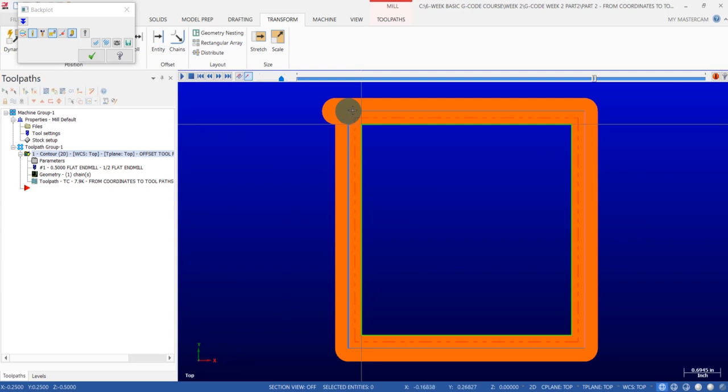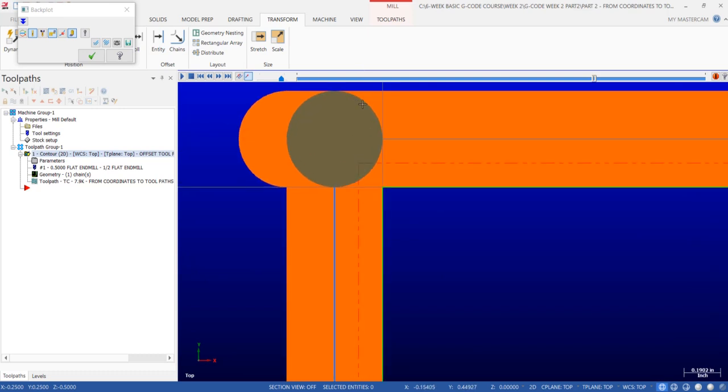And we moved a 1/4 inch past the part, but if I zoom in, you can see this is the cutting edge of the tool, and it has actually moved 250 thousandths past the part. Had you moved 100 thousandths past the part, that would have been sufficient, and that's where you would retract your Z axis.